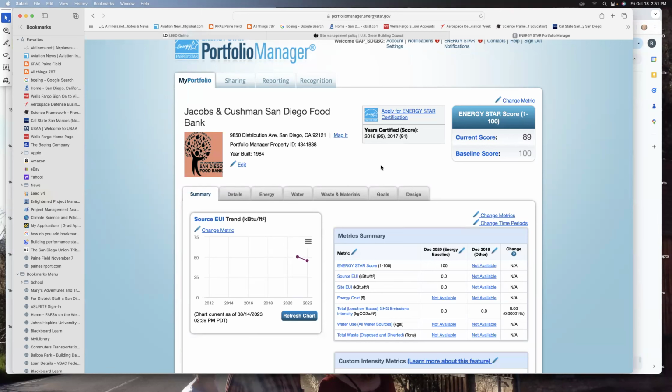All right, so that's that. That's an integral tool you need for the energy performance of the building. Again, the way you're meeting the prerequisite is the same way you're meeting the actual credit. You're just using that Energy Star score. In our case, we were above 75, and we got a lot of points because at the time we were at 100, so we got the total 20 points. Right now, when we go into it, we'll see what they would have gotten. It's a great benchmarking tool, and a lot of benchmarking ordinances in cities use Energy Star Portfolio Manager, so that's pretty awesome.